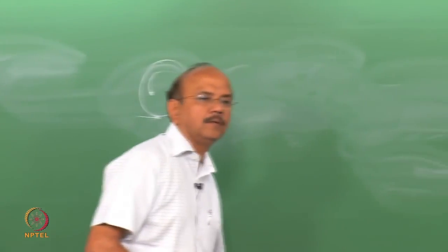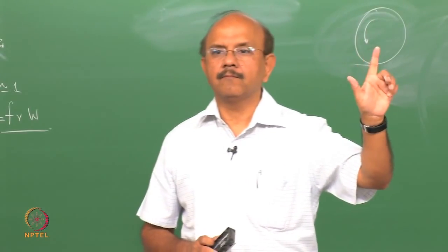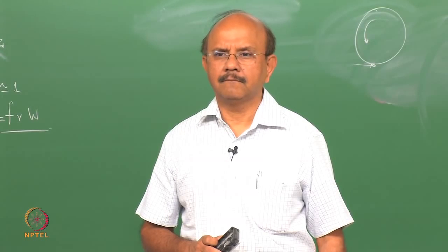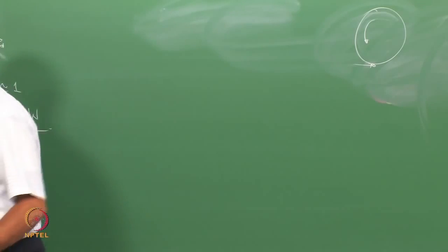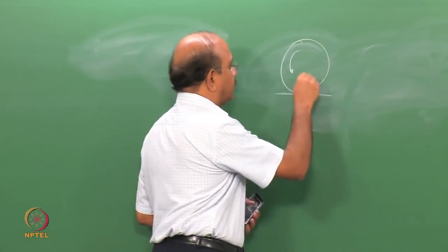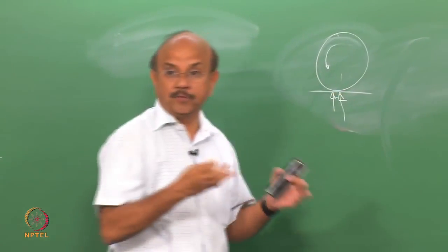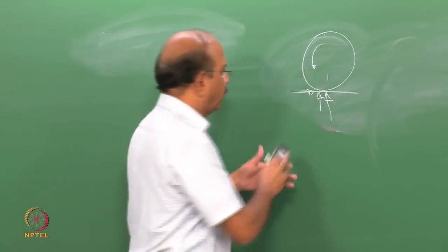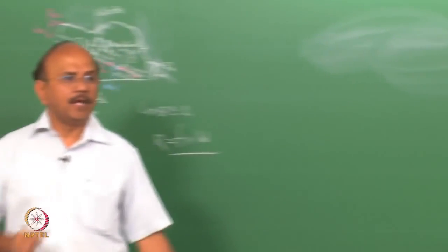Now we will write down the equilibrium equations. Earlier we said rolling resistance is created due to normal force, but in the final free body diagram we are putting both normal force and, yes, this is normal force, of course, exactly. So that's what I just pointed out, that we had a force which is away. When I want to now shift it to the center, then the normal force will still be there, plus a moment, and the moment becomes the horizontal force, and the normal force is still there. So that's a reaction force, has to be there, okay? That's the reaction force. Let's continue now.